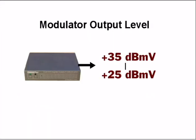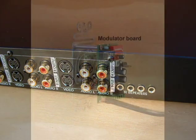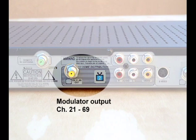Modulator output levels are usually high, typically 25 to 35 dBmV. This comes in handy since they're usually placed in the internal path of a coax distribution system where losses are high before reaching a distribution amplifier. Newer modulators can support S-video as well as component video and stereo audio. They also provide a loop-through capability on the inputs. Modulators can also be built directly into camera modules. And new Dish Network satellite receivers are equipped with a frequency agile modulator for off-air channels 21 through 69.